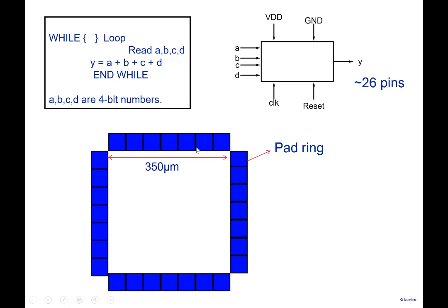So what you see here is we have 7 here, and we have basically a 28-pin IC. 28-pin packages are available. Packages don't come in odd numbers. You can't go and buy a package which gives you 13 pins or 23 pins and all that. Packages have been designed of certain sizes. So 28-pin packages are available. So whatever IC we are designing, we could try and fit it into this 28-pin package here.